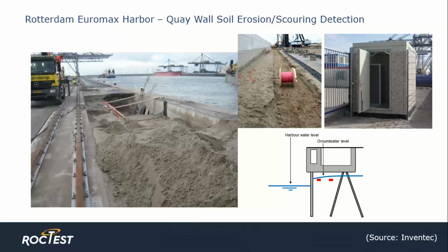SMARTProfile distributed strain sensor was directly embedded into soil during construction phases with the aim to detect backfill degradation and analyze the evolution of soil settlement. Continuous automatic monitoring with alarms was performed during both the construction phase and throughout the full normal operation. The system allowed for effective detection and location of settlement areas during the early operational phase. At the bottom right, you can see the 2 SMARTProfile fibers installed longitudinally at the normal groundwater elevation. The fibers are shown in red.